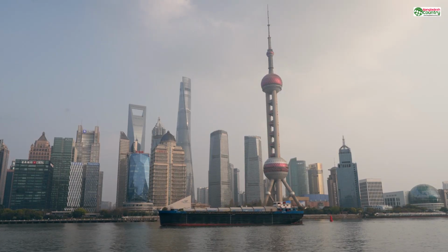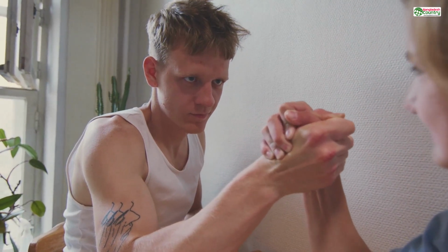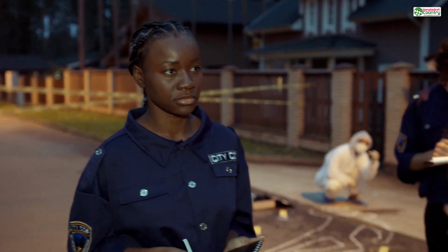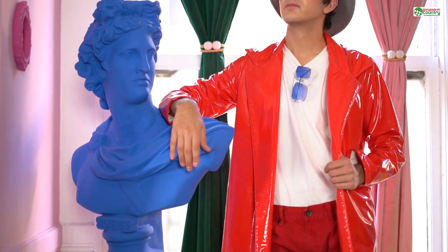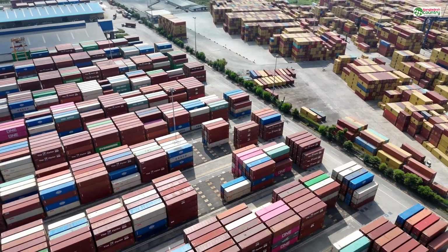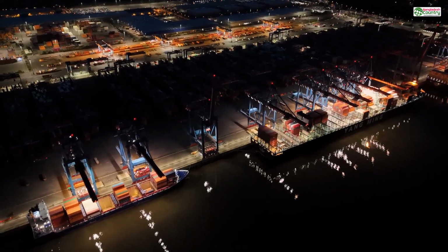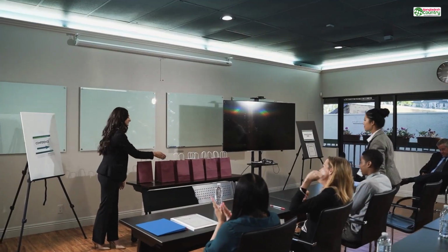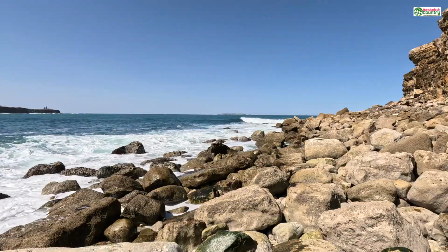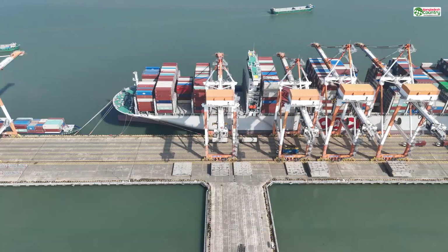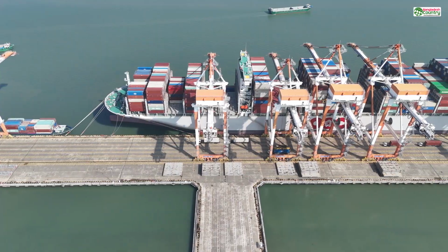Now let's say you've done everything right. You set your scene to millimeters. You meticulously modeled your object to the exact size you want. You are ready to export. You hit export as STL, and you're presented with a pop-up window full of checkboxes and number fields. This is the final gatekeeper, and it's where so many people stumble. In this export dialog, you need to look for two things. The first is a scale setting.